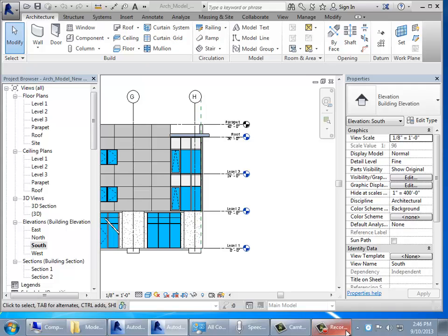I can put things above or below the level, but that's kind of the limit of control. So if at the mezzanine level there's furniture or equipment or things that actually sit at that level, such that if the mezzanine moves up or down they should move too, you don't want to say it's level 1 plus H. It actually is its own distinct reference point. There are things that will push you towards saying, that's sounding like a real level, and push you over the edge to make it a real level, so that if I move it, everything follows.